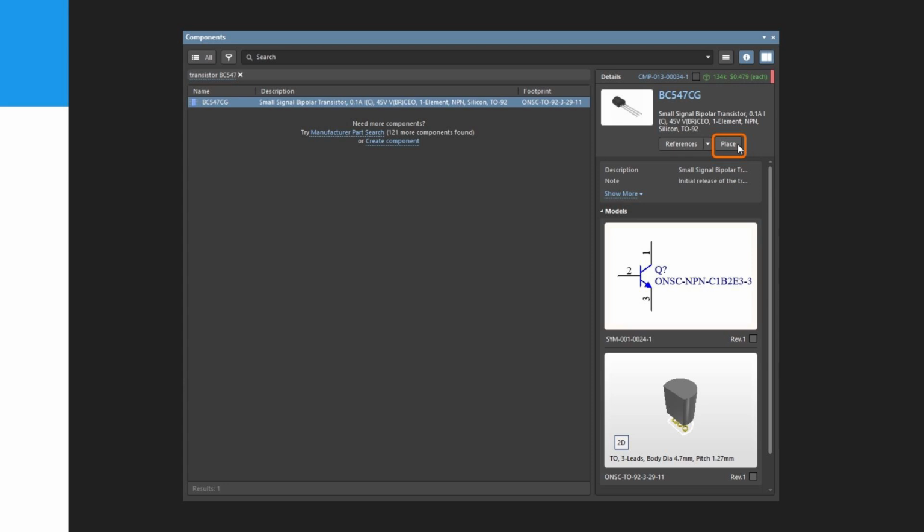Press the Page Up key twice to zoom in two steps. You should now be able to see the grid lines. Then, once you have positioned the part, click the left mouse button or press Enter to place Q2. Once again, a copy of the transistors you are holding will be placed on the schematic and the next transistor will be floating on the cursor, ready to be placed.